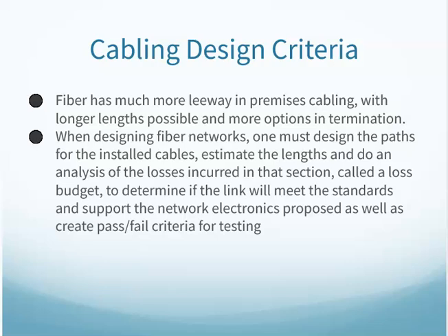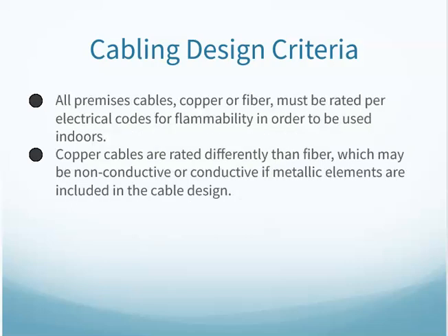So with that, when they install fiber, you need to estimate the lengths and any loss of that installed cable. That way you know if it'll meet the performance criteria for that link. That is actually a calculation you can do.